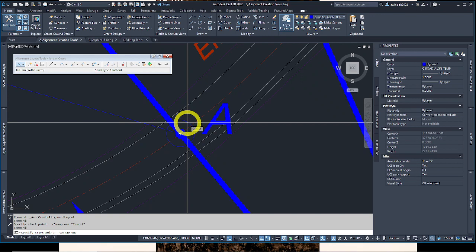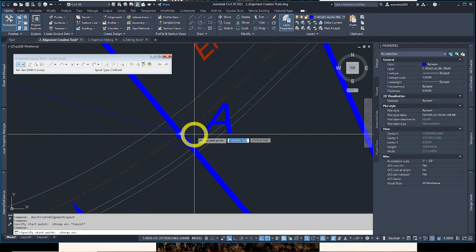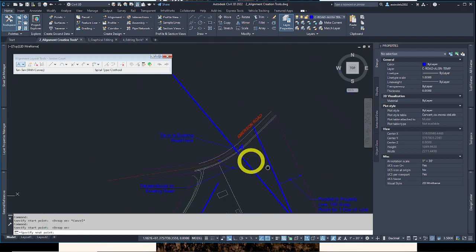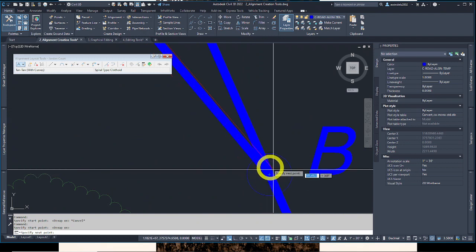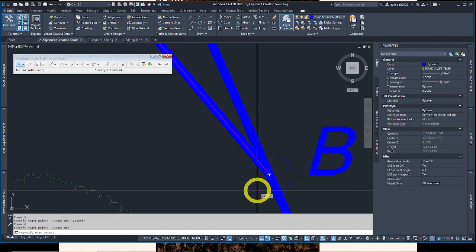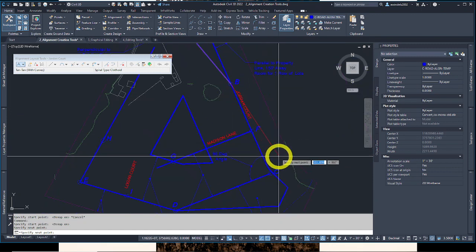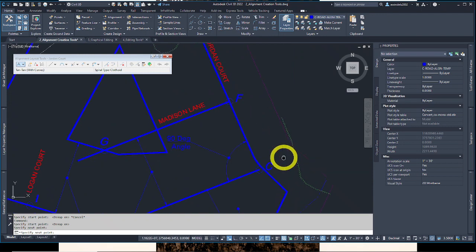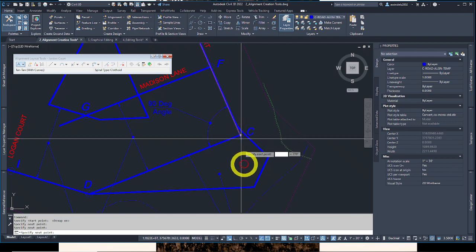So we see when I snap, whatever you hover near, it will want to snap to. So when I hover near this circle edge, it wants to snap to its center. So I'll pick A. I'll hover, or if I go right on the center, but there's other things in here too. You get snapping, and what you snap to, you got to be very careful on AutoCAD. That's a skill for sure. You get better at it. We'll hover near the periphery of the circle, pick B, and then we will pick, I believe it has to go right to C. Yes, it did. Center.